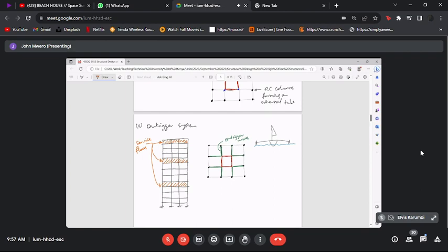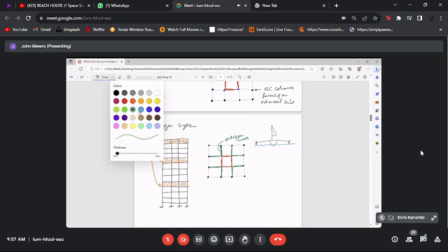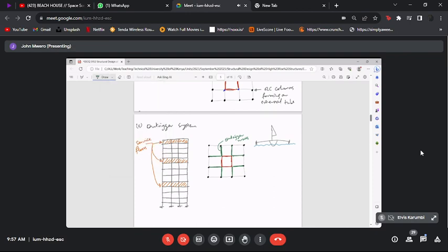Now, these service floors are not usually designed to be occupied by human beings. They are only spaces for equipment, like water tanks, etc. So you can easily throw in walls in this manner that we have shown here, without having to have provisions for movement of people or spaces for lighting. So that's an outrigger system.